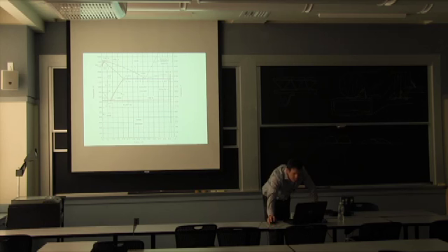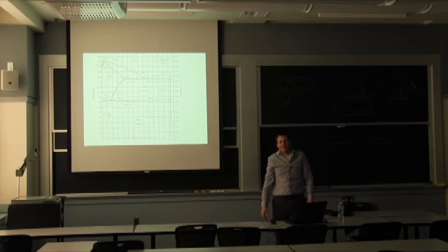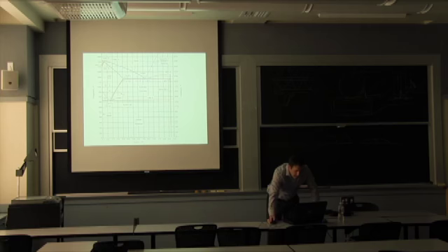So at that temperature, you start to solidify. I say start because you can see here that there is some liquid, well, no, if it's pure, okay, so you solidify. Let's start with that one. You're in the delta phase. The delta phase, I can't show you a micrograph of it because it transforms back to another phase later. It's only a very high temperature phase of steel. After the delta phase, you have the austenite